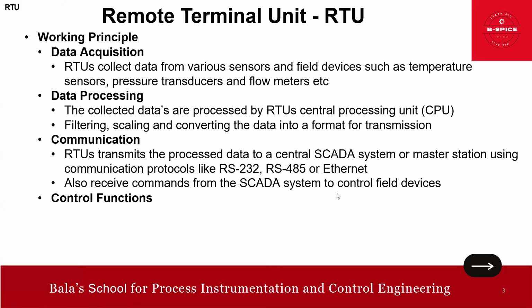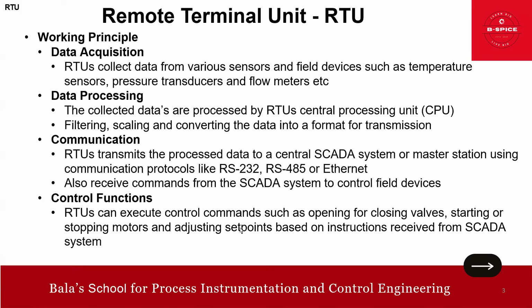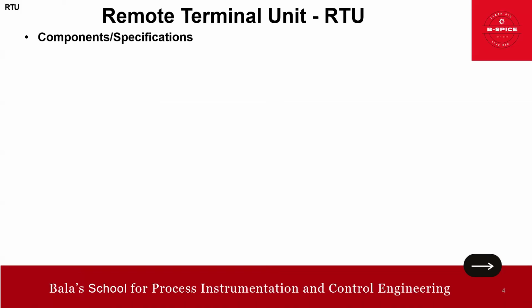And when we talk about the control function, RTU can execute control commands such as opening or closing the valves, stopping the motors, and adjusting the set point based on instructions received from the SCADA system. So these are the working principles. When you talk about the RTU's working principle, just focus on these items: acquisition, processing, communication, and control, friends. As simple as that, right? Okay. Now we go into the components and the specifications.